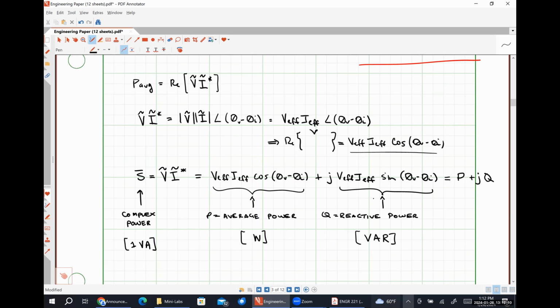So we were talking, I think just Wednesday, about how the average power absorbed by an inductor or the average power absorbed by a capacitor is zero, because exactly half of the time the element is absorbing power and exactly half of the time the element is sending that power back to the source. The reactive power is what takes care of that action, okay? So it's simply temporary energy storage in our system, okay? Even though it's imaginary, which is a whole nother bag of cats, all that really means is that it's 90 degrees out of phase with the real stuff.